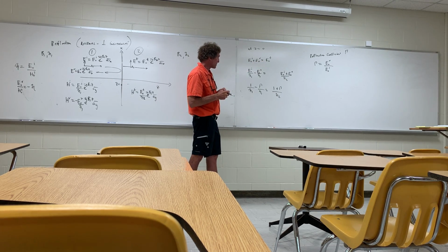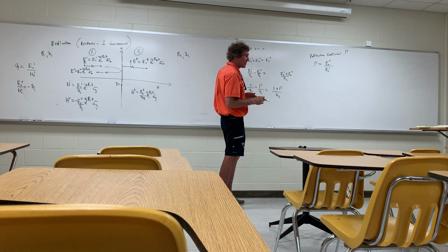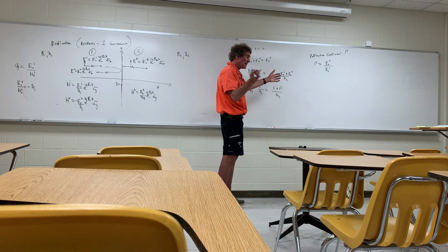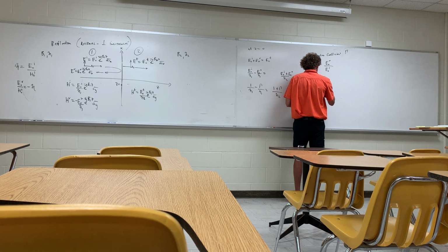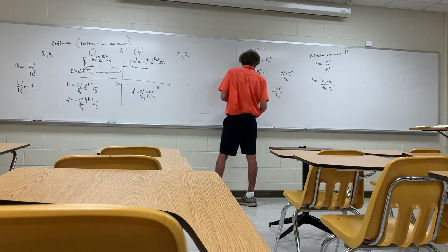That's the important symbol. Now I'm going to move things around so I define the reflection coefficient in terms of eta 2 and eta 1. You can do this a couple of ways. We could multiply both sides by eta 1 eta 2, and I'd have eta 2 here, eta 2 here, eta 1 here, eta 1 here, and then collect terms. If you do it, you find it's eta 2 minus eta 1 over eta 2 plus eta 1. You can do that fairly straightforwardly.